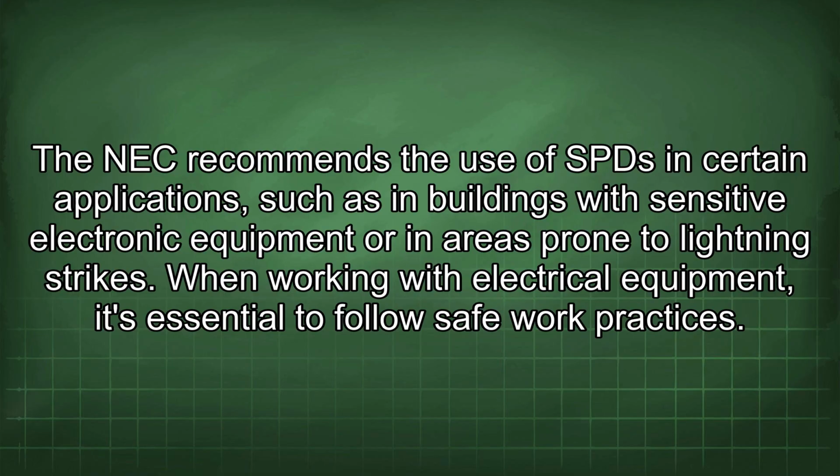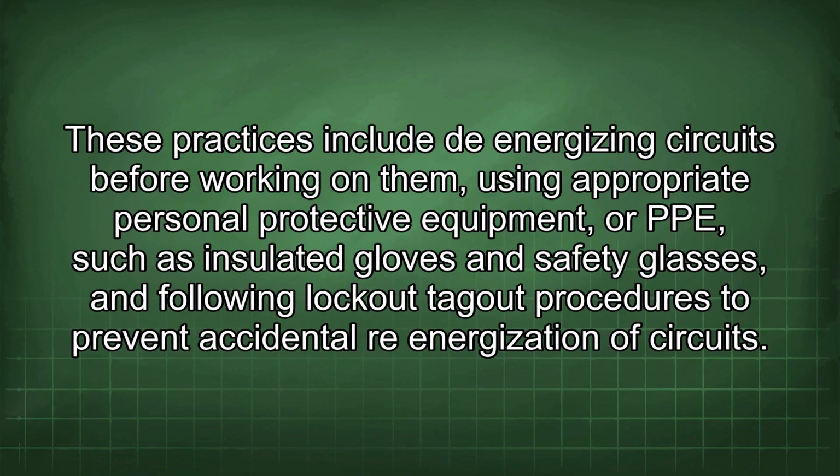When working with electrical equipment, it's essential to follow safe work practices. These practices include de-energizing circuits before working on them, using appropriate personal protective equipment, or PPE, such as insulated gloves and safety glasses, and following lockout-tagout procedures to prevent accidental re-energization of circuits.